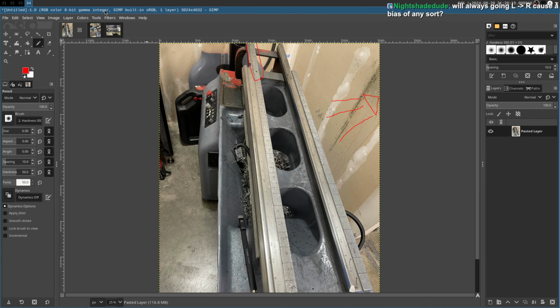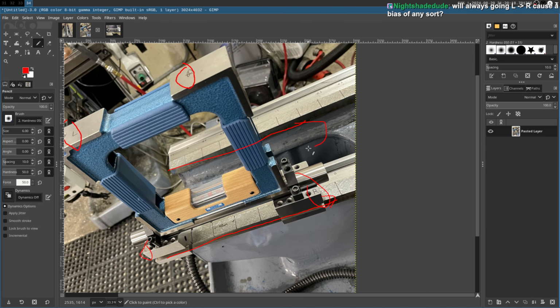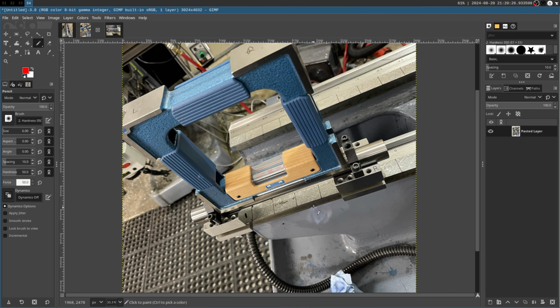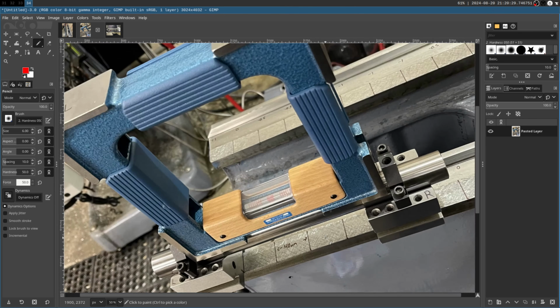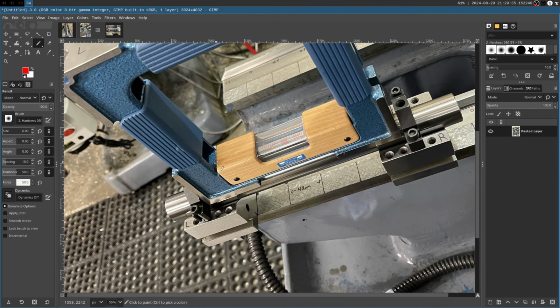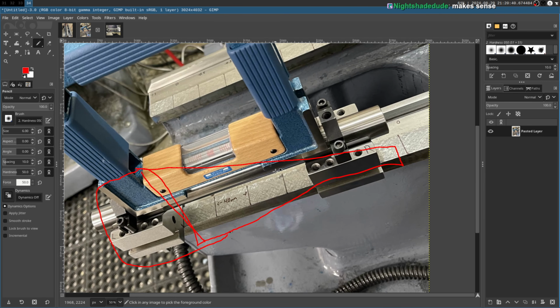Will always going left to right cause a bias of any sorts? No. In absolute terms, yes. But since we're only caring about the relative measurements, I'm making sure that I'm measuring in the same way, such that if this was a wedge, let's imagine that this whole level setup is on this massive wedge, the wedge is facing the same direction for all the measurements, right? Now, that doesn't mean that what I'm measuring is level, but it means that if this dips down...